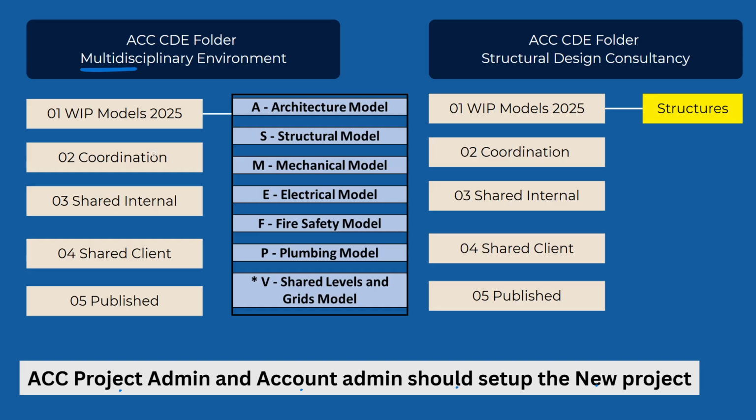So you should know that, you should tell in the interview how to set up the ACC projects by using ACC template, that is a standard template which contains all the folder structure and roles. Why I said roles means, obviously, you have architectural information author, architectural task team manager, task team information manager, structural modeler. You have different types of roles, right? You can load all the roles and give access to, let's say, for architectural people, architectural roles, you can give access to architectural folder.